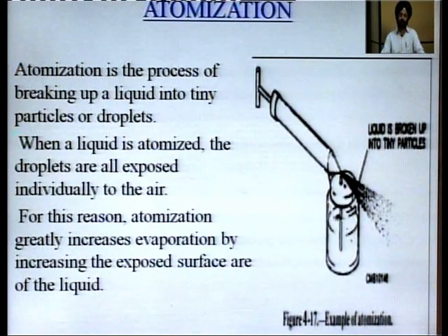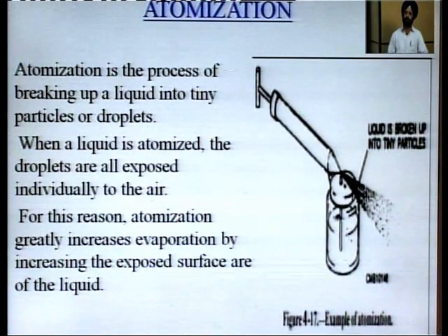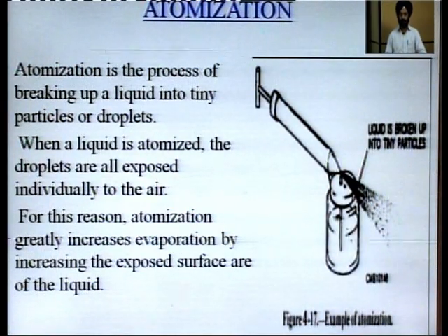So this is atomization. This is very important. We must clearly understand that the fuel is mixed with the air in atomized form. If it is not in atomized form, the combustion will be improper and the fuel will go unburnt or semi-burnt into the atmosphere. We will lose in the energy sector also, and then it will cause pollution. The unburnt carbon will result in carbon monoxide and sulfur oxide. These are very poisonous.